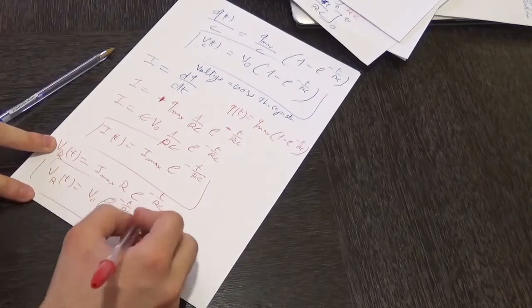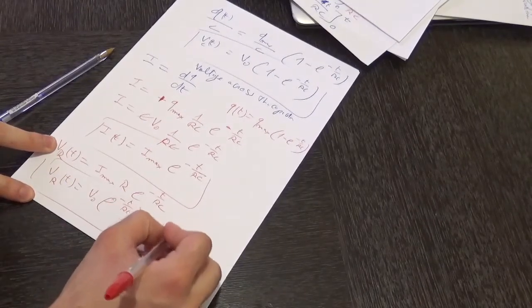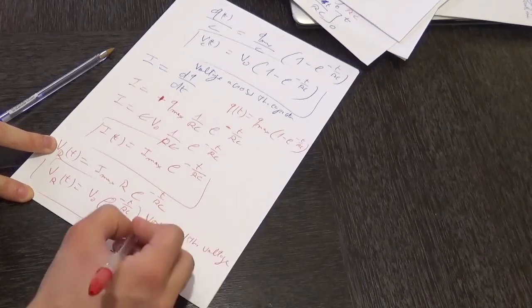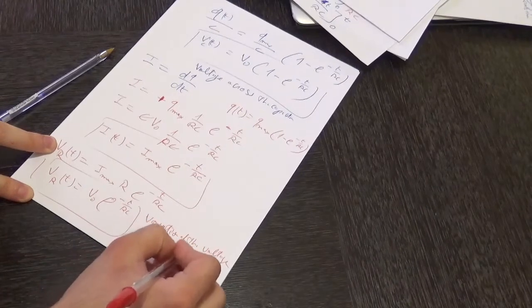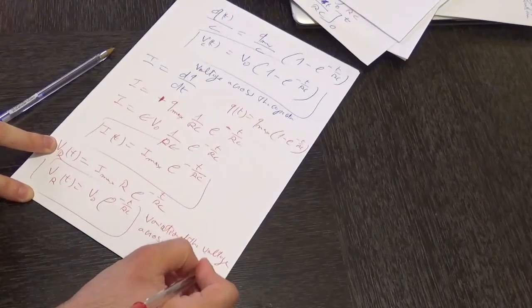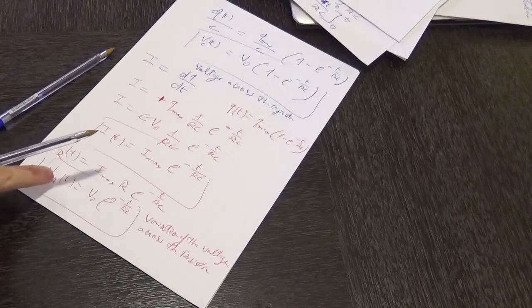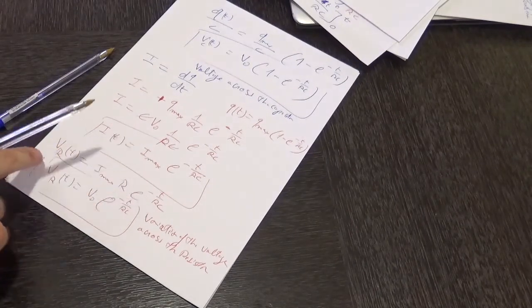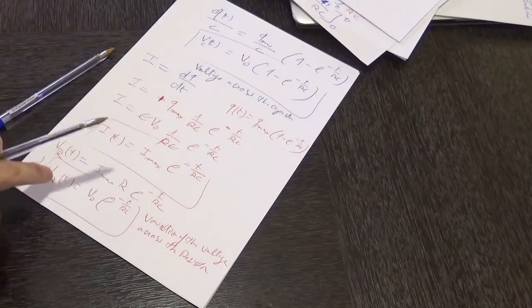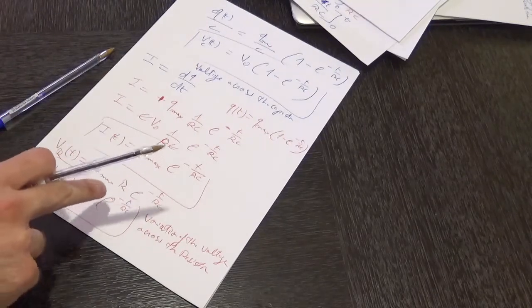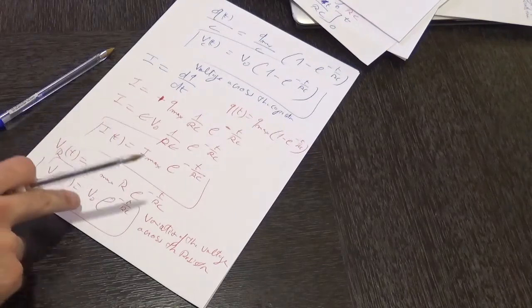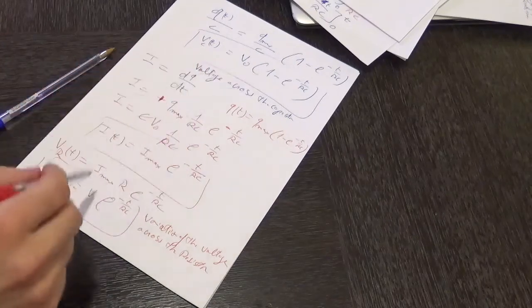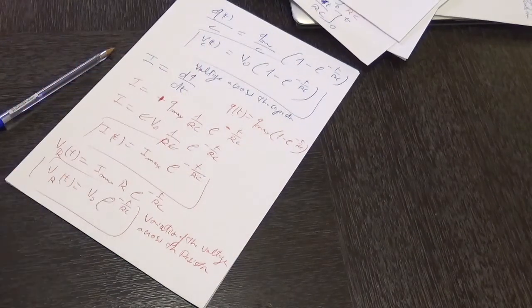And that would be an equation for the variation of the voltage across the resistor. As we can see over here, the variation for the voltage across the resistor is basically a decaying one. So whenever the capacitor is undergoing a charging process, the voltage across the resistor would be decaying. But moreover, if we have a look at the voltage across the resistor and the voltage across the capacitor, they both have an exponential response.